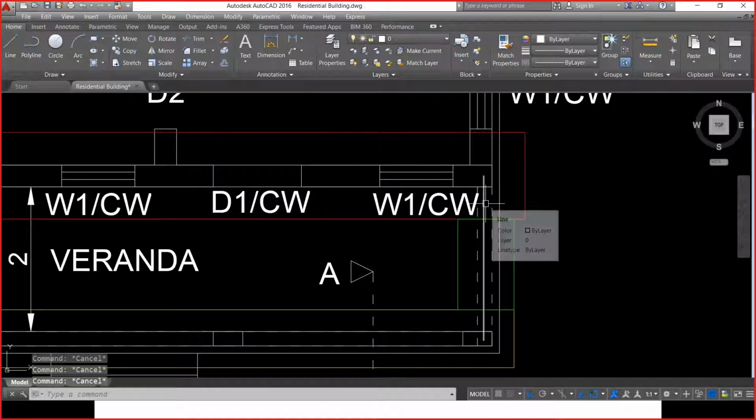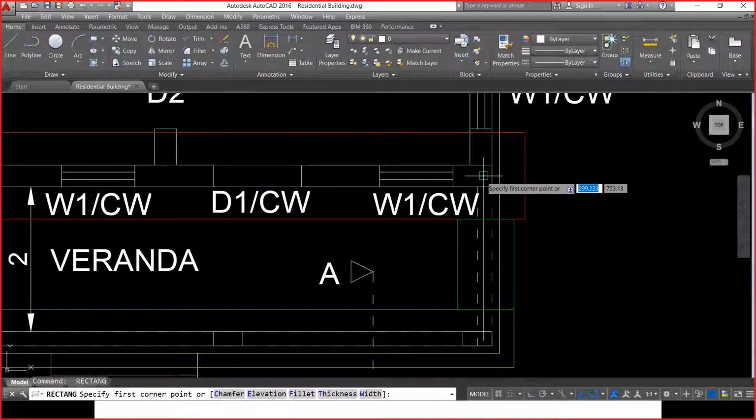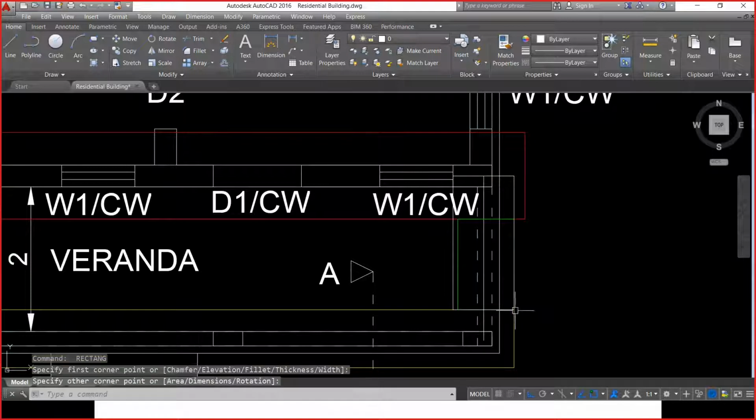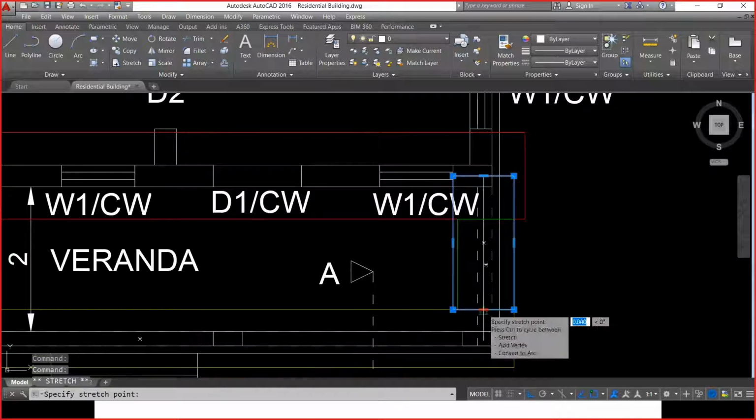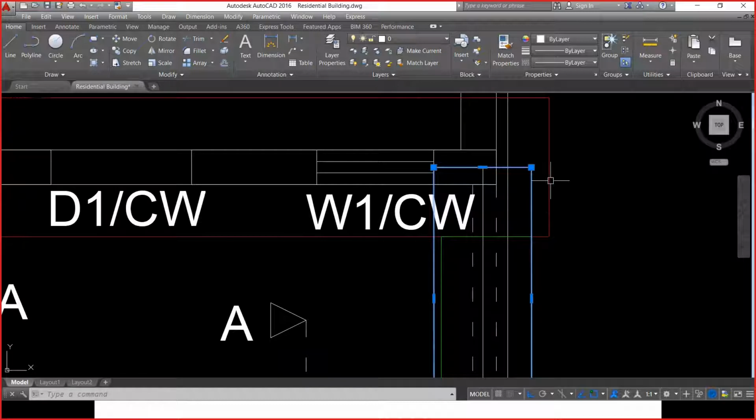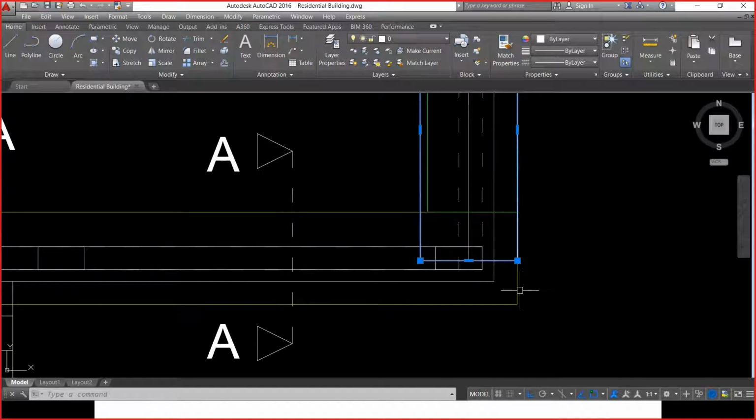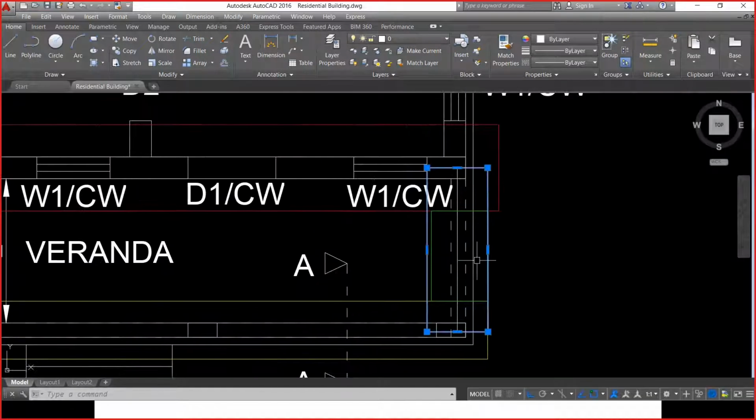Now, if I calculate the length, this is the total length. Center to center distance is 2.25 meters. 2.25 multiplied by width multiplied by depth. If I do that, I'll be calculating the total quantity for this area, which is just indicated in white color now, which is being highlighted. But that is going to be a wrong value because this portion is already being excavated. As you can observe, this portion under the red is already excavated and this portion under yellow is also already excavated. So I need to do the deduction for this area here and this area here.